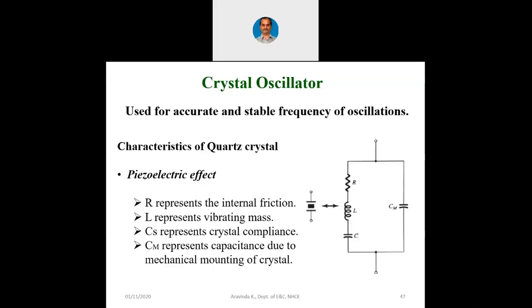radio frequency. But the problem with those Hartley and Colpitts oscillators is we are using again reactive components, and all these reactive components will have tolerances. Because of the tolerances, even though we design a Hartley oscillator for a very accurate frequency, when we connect those components, because of the component tolerances, we may not get the very accurate frequency. If at all we have to get a very accurate frequency, then we should go for minimum tolerant component values. That was the challenge there.